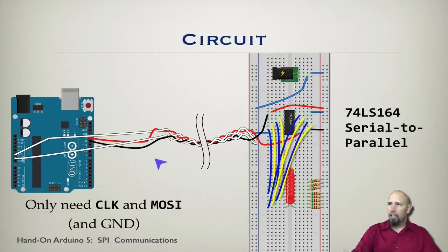In our case, the grounds basically are part of the twisted pairs that we use for this example. The twisted pairs are used to provide at least a minimal level of shielding against noise. In our example, I'm going to use a pair of twisted pair cables, and they're about 2 meters long, roughly 6 feet.